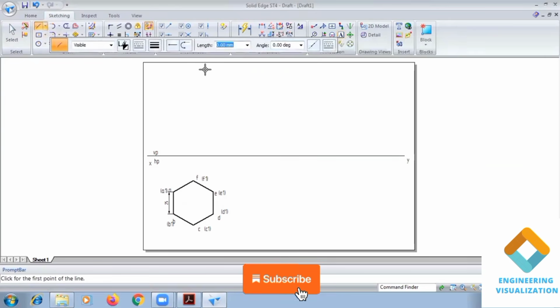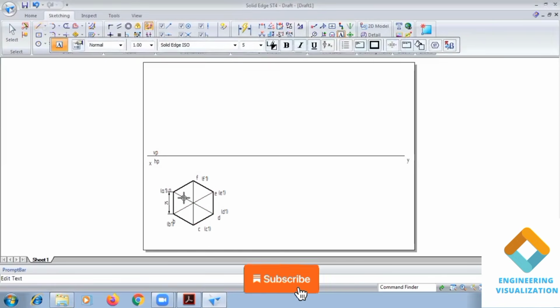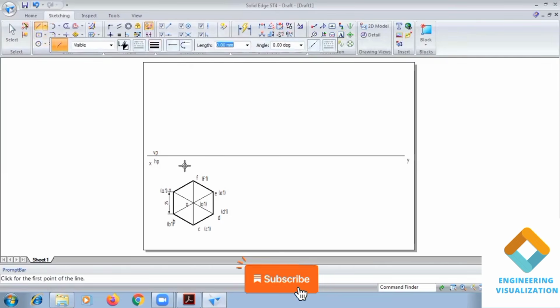After this, we draw the thin lines to find out the center of the axis. Okay, that is diagonals we are going to draw. It is O. Okay, now here axis length is 50 mm.